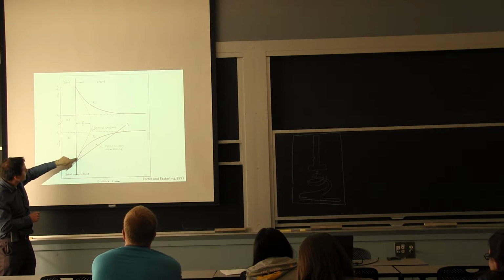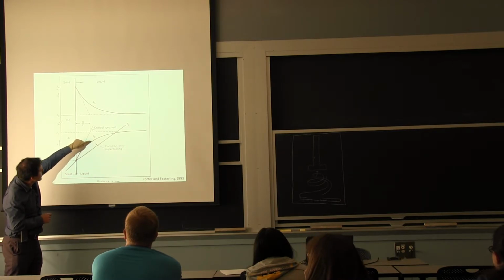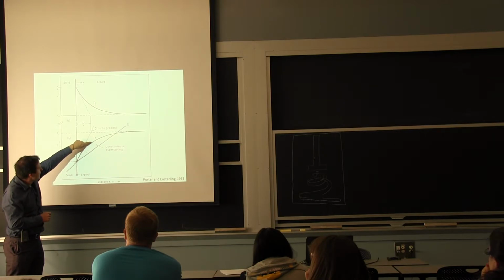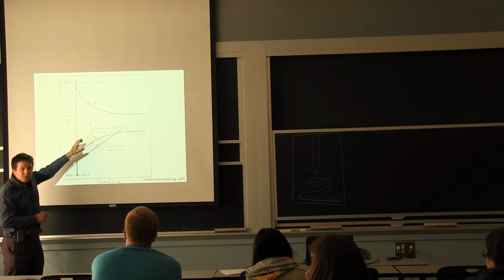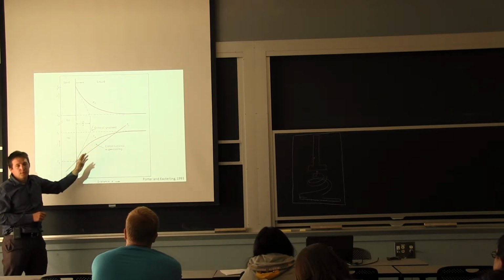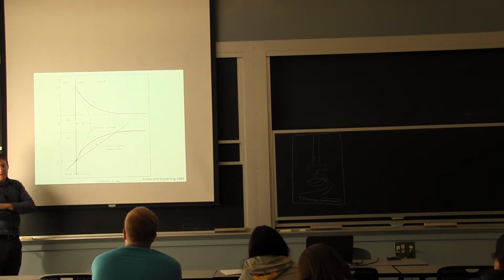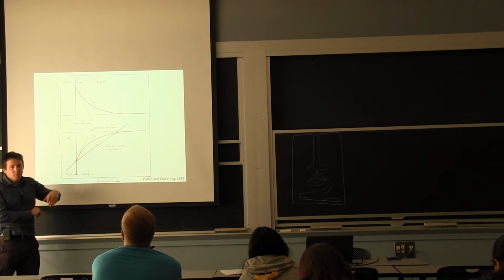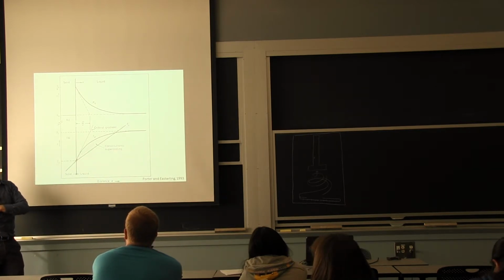So what you find here is that you are far below; this is the temperature where this composition will start to solidify, but you're actually at this temperature, so now you have an offset when you are located ahead of your solidification front. And that's what leads to this directionality in the formation of dendrites. And sometimes you can also start forming other crystals ahead if you're fast enough in your cooling rate.